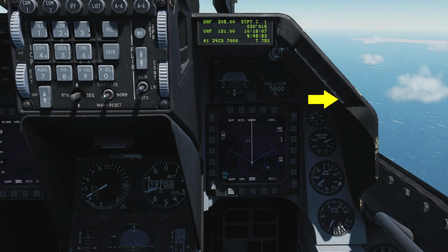The canopy light is lit when the canopy is not down and locked, and the low oxygen light will illuminate if the oxygen system is below 5 psi or there's a bit test failure. The engine is equipped with a self-contained oil system to lubricate the engine and the gearbox. The indicator reads between 0 and 100 psi. The normal idle throttle psi on the ground is about 15, and at military power and above about 60.